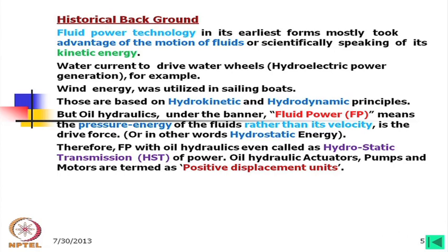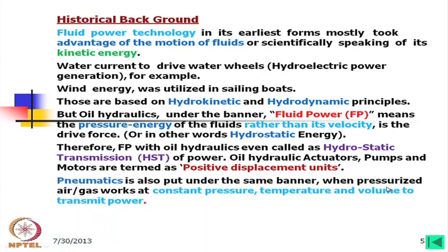The question is, do we use any hydrokinetic principle of fluids in the case of fluid power? The answer is yes. When we are analyzing the valve flow, particularly flow in and flow out, we also have to use the hydrokinetic part. But as far as power transmission is concerned, we are using only hydrostatic power. Pneumatics is also put under the same banner, when pressurized air or gas works at constant pressure, temperature and volume to transmit power.